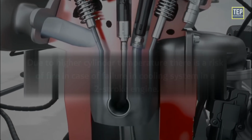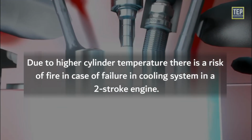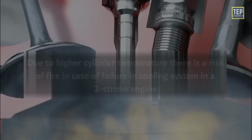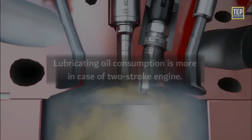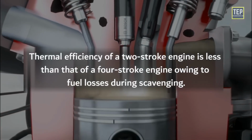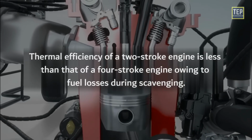Disadvantages. Due to higher cylinder temperature, there is a risk of fire in case of failure in the cooling system in a two-stroke engine. Lubricating oil consumption is more in a two-stroke engine. Thermal efficiency of a two-stroke engine is less than that of a four-stroke engine owing to fuel losses during scavenging.